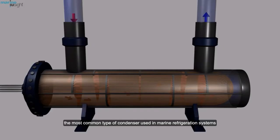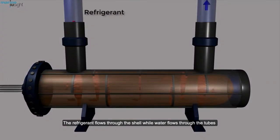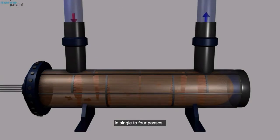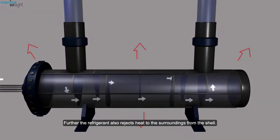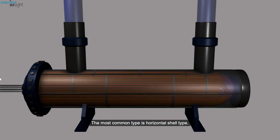The most common type of condenser, used in marine refrigeration systems, is the shell and tube type condenser. The refrigerant flows through the shell, while water flows through the tubes, in single to 4 passes. There might be a vent connecting the receiver to the condenser for a smooth drainage of liquid refrigerant. The shell also acts as a receiver. Further, the refrigerant also rejects heat to the surroundings from the shell. The most common type is the horizontal shell type.